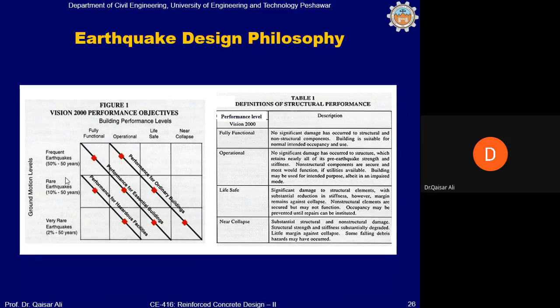So when the probability of non-occurrence is 98% and only 2% occurrence probability, it would be highly questionable to design our structure such that no cracking occurs, because the initial investment will be very high, and people will not be able to design and construct their structures. The initial cost of the construction will be too high, unmanageable and uncontrollable. For this reason, some risk is always accepted, and this we do in our daily routine life.